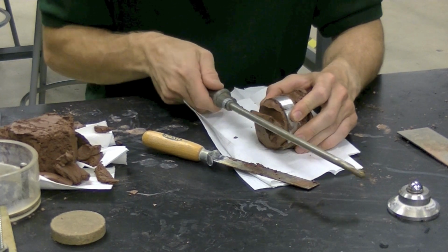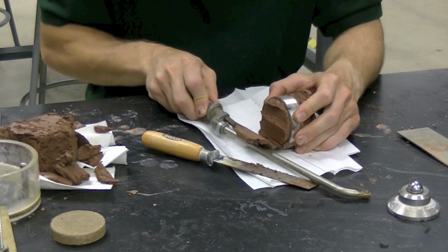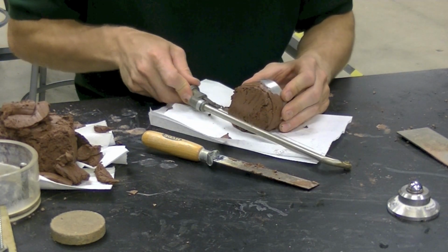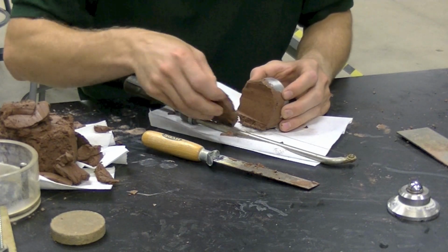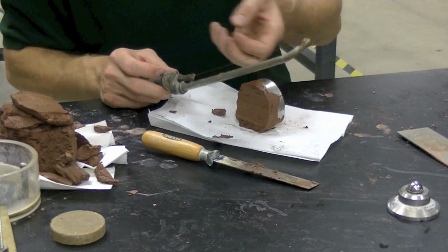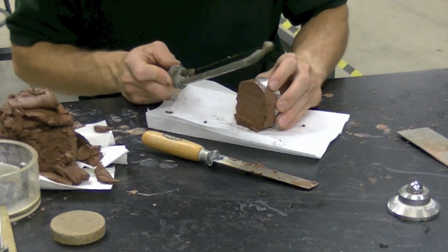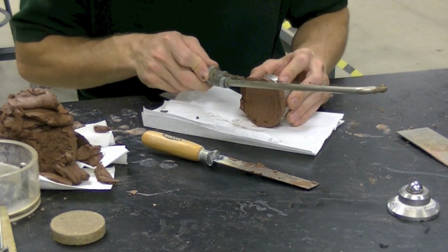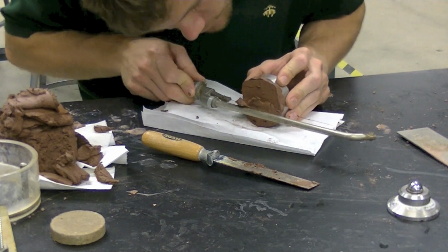For soft specimens, use the wire saw to flush the sample with the flat surface of the ring. The wire saw reduces smears on soft soils. The wire saw is used here because the sample is considered a soft clay. Saw or trim the specimen until the sides are flush with the ends of the ring.